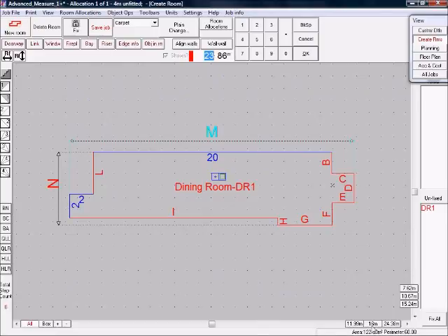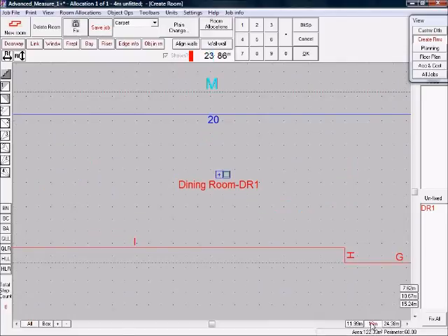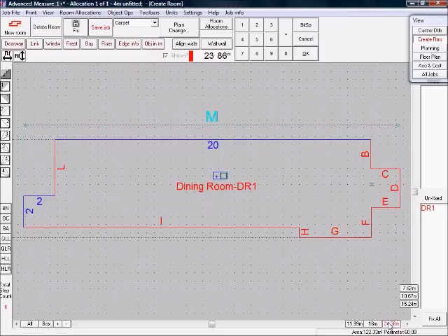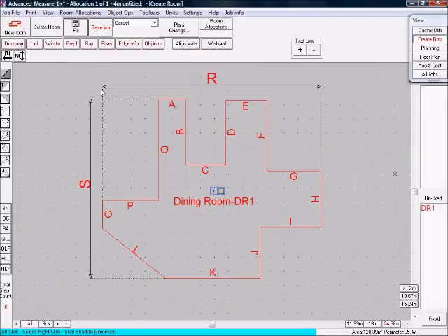Another useful feature for a complex shape is to have a reference wall and do a set of running measures from this reference wall. For instance, with this complex shape here, I might say this wall is the reference wall. I can declare this is what I want by dragging on this reference wall designator. Now you see that straddle dimensions have automatically been drawn from this reference wall to all the other walls which need them. I can now dimension this straddle with the running measures.